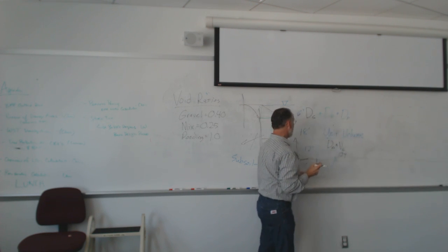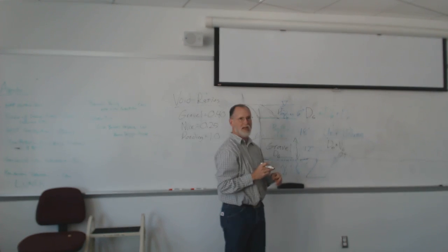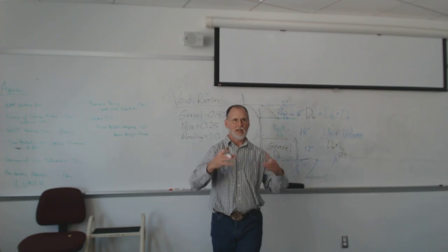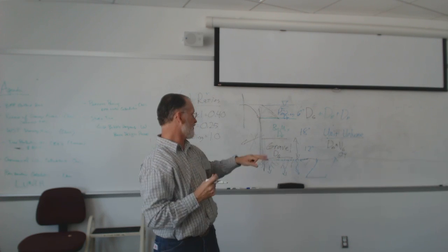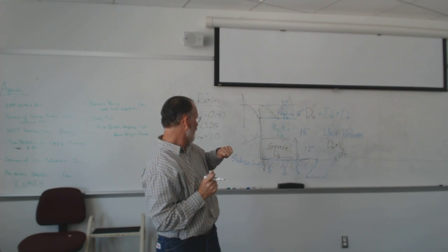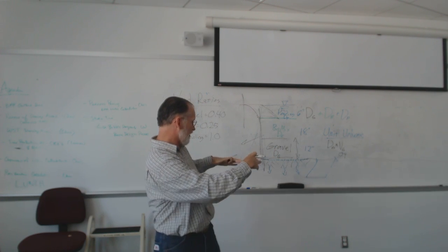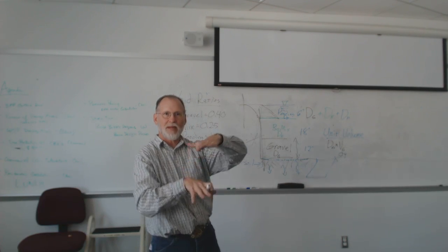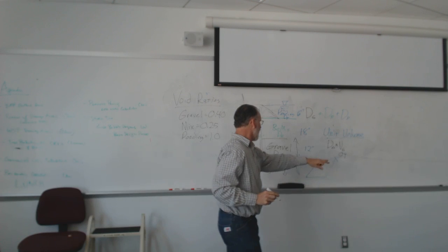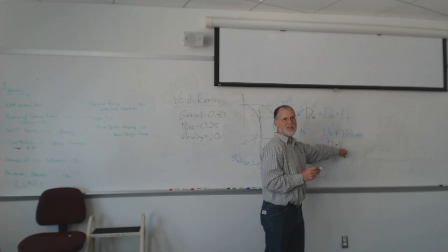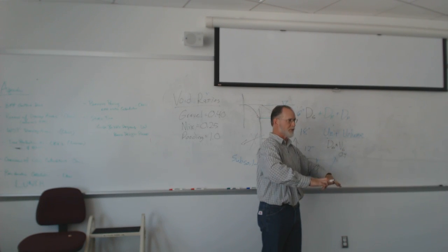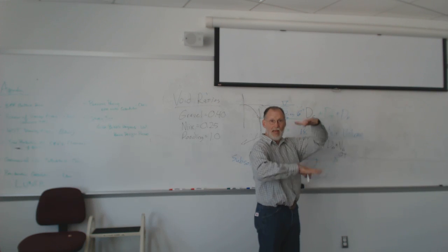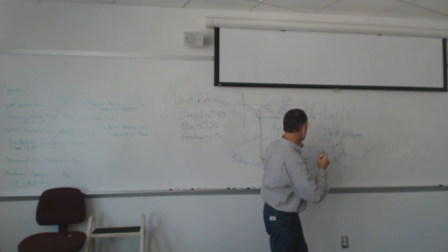That's going to give me the volume of gravel I've got, per cubic feet. This is on a 1 square foot basis, so this is on a 1 square foot footprint. I need to multiply that times my depth to get it in 3 dimensions, to get cubic feet.